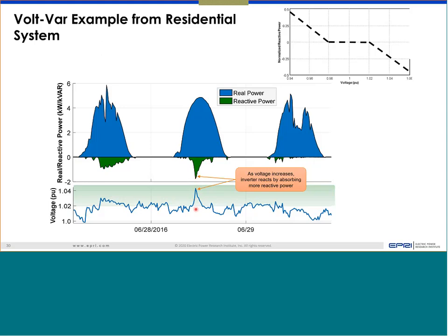Not necessarily they'll be able to bring the voltage within your target range. So it helps, it tries to regulate the voltage or keep it at the target level, but not necessarily will it be able to, because that depends on a lot of other factors. And here it is defined from the regulators that you typically use. If I'm not mistaken, I'm not the expert, but a regulator keeps on changing the tap positions until it brings the voltage within the acceptable tolerance, like your target range, or it maximizes step size or final step. But it keeps on trying within a certain time interval.